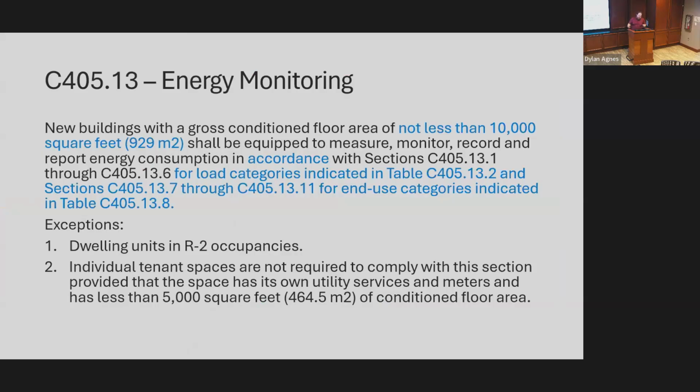So energy monitoring, 405.3. This is a new section that got added in 21. It was updated in 24, so that not less than 10,000 square feet shall be put to measure, monitor, record, and report energy consumption in accordance with the section for the appropriate load categories listed in that table. And then there's a bunch of end use categories. I'm going to go through all that, don't worry. But basically, this was added in 21, and what changed was the square footage requirement.